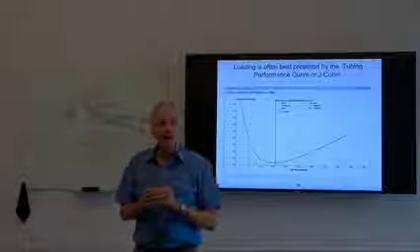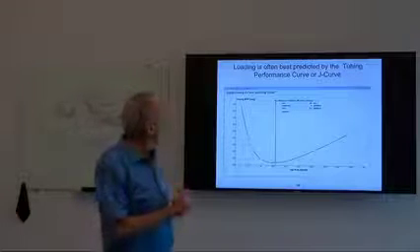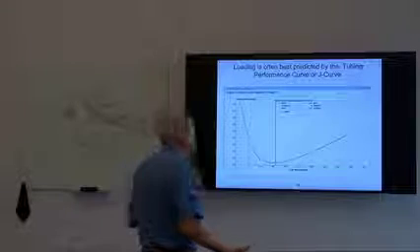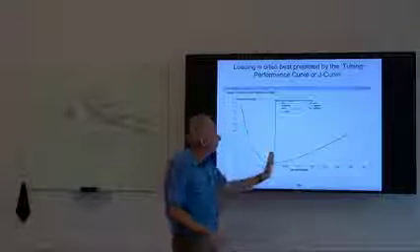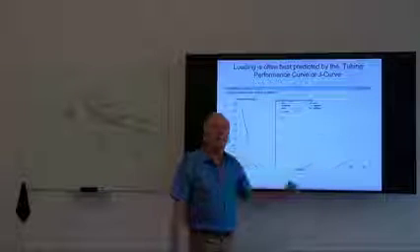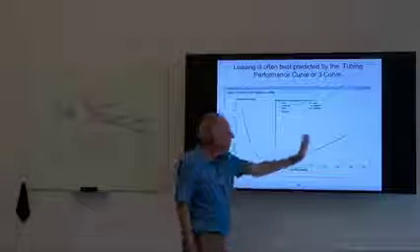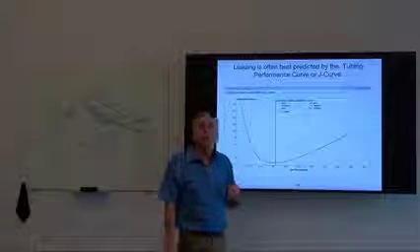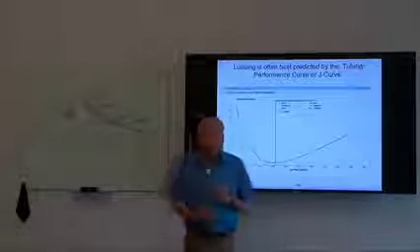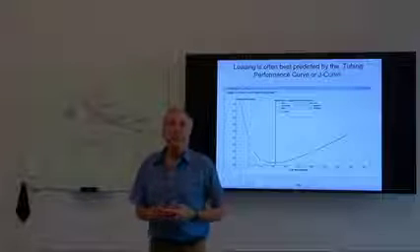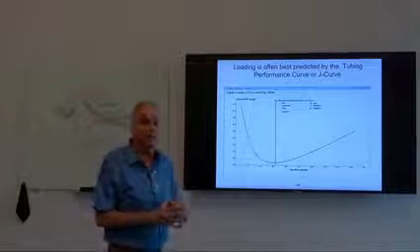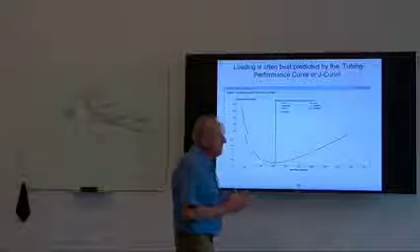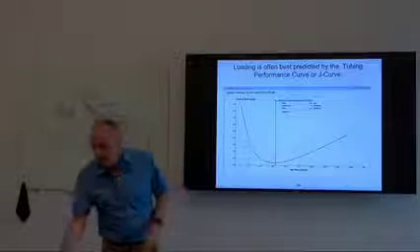once upon a time, there was at least the description of loading versus unloading, or stable versus unstable flow. Everything to the right of the minima, the minimum point, was considered stable flow, and everything to the left was unstable flow. What we've observed empirically over years of looking at a very large number of wells and data sets is that that isn't necessarily true.